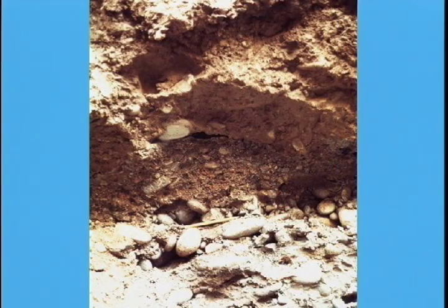Here is another photograph taken of the bottom of the blanket. Only coarse blanket material remains, just above where the blanket material contacted the foundation cobble gravel. Void space exists between the washed blanket material and the intact blanket. Washing out of fines from the blanket presumably will continue with time, and a sinkhole will become evident at the surface.